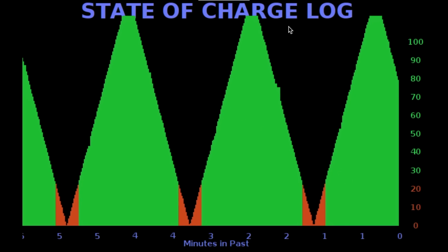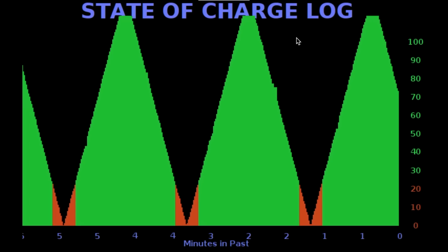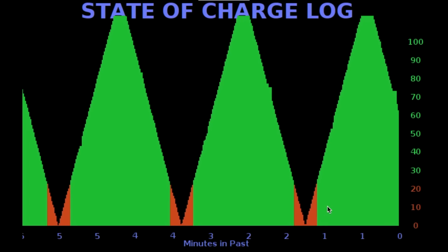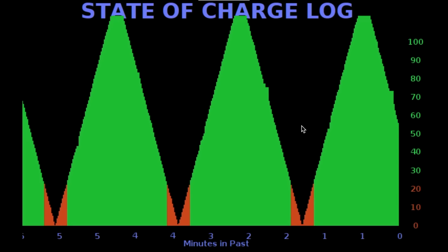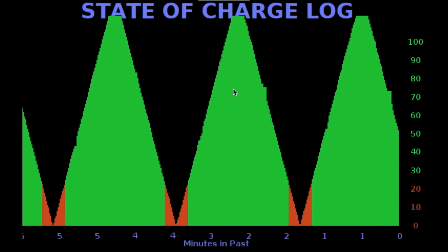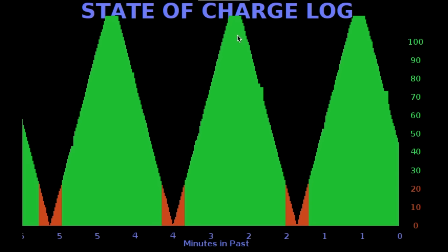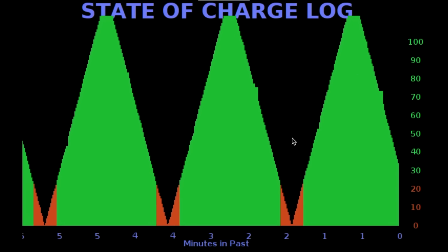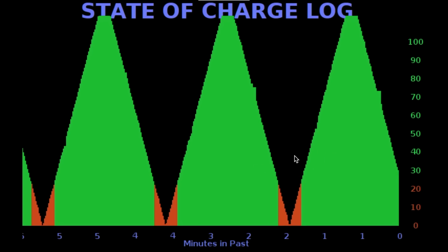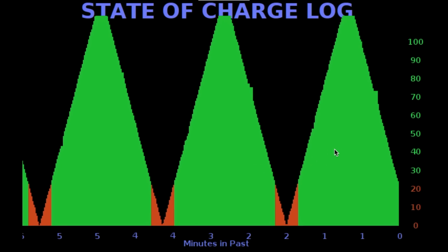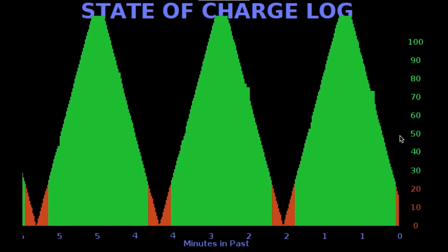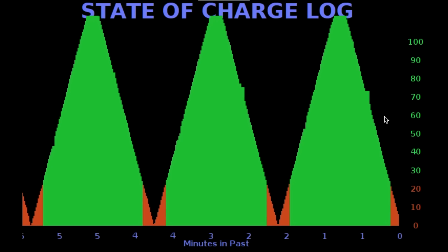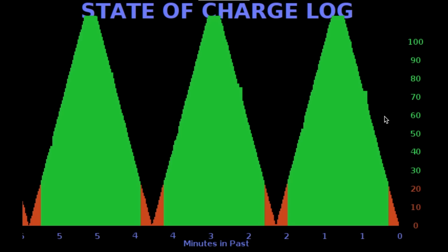And if you get the full charge in the afternoons when you have solar, and full discharge overnight, your battery's too small. You want it to charge to about 80% or 90% in the afternoon, and discharge to 30 or 40% overnight. That would be ideal, and it gives you some slack for days when you don't have enough sun to really do anything.